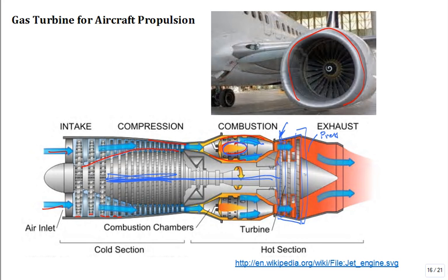Put it through a nozzle. Now you have a nozzle. What's the purpose of the nozzle? Increase the velocity. Increase that kinetic energy. Convert from the enthalpy to kinetic energy. The kinetic energy is proportional to velocity squared. Get a high velocity because you want to throw these exhaust gases out at a high velocity.